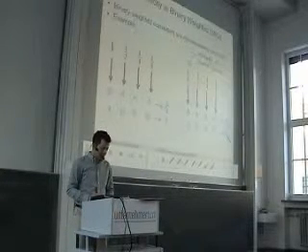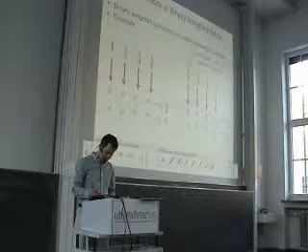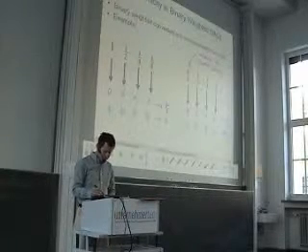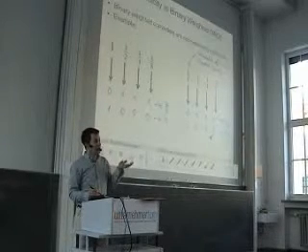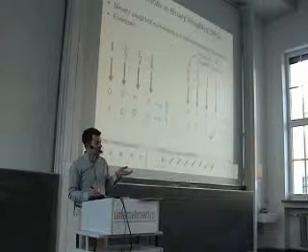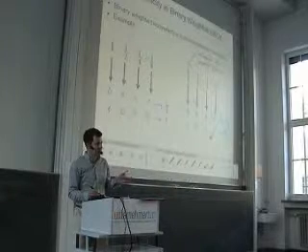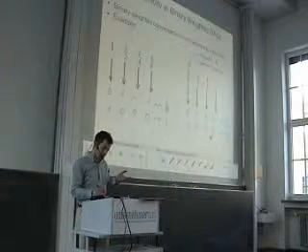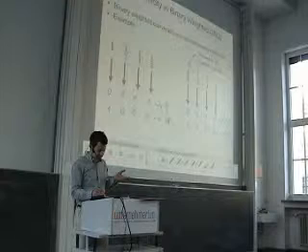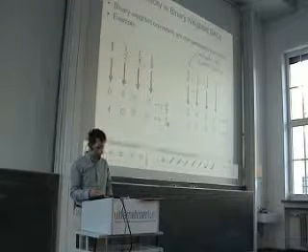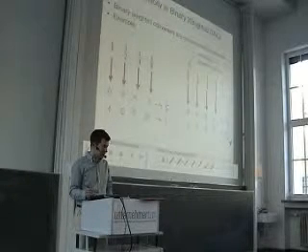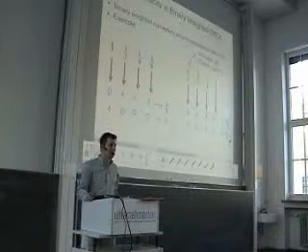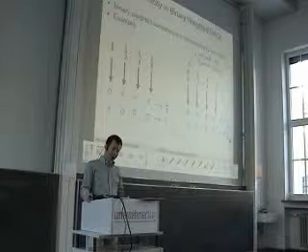What happens here? We increment the input. So from here to here, we go up by 1 LSB. And what we expect is that we go also up by 1 VLSB. This happens here. Here we go up by 1 VLSB. However, here you can see we go even down. And this is this non-monotonic behavior I mentioned last week.